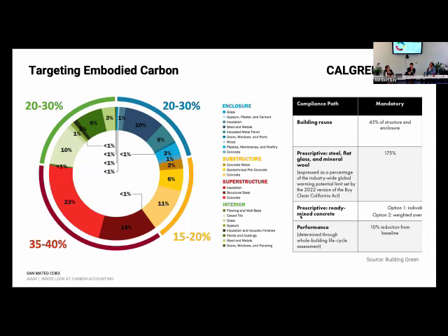And then again, I've seen folks pull info from EC3 and say, look, there's 3 people who can meet this, but guess what? They're not part of our standard supply chain here locally in California. Just because it's available in Europe doesn't mean that it's feasible to get it here locally. So approach using that tool with an extra layer of caution and understand it's a starting point and not the final decision maker for compliance.